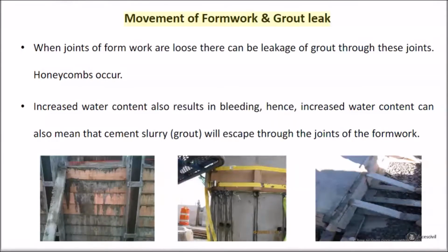Movement of formwork and grout leak. When joints of formwork are loose, there can be leakage of grout through these joints. Honeycombs occur. Increased water content also results in bleeding, hence, increased water content can also mean that cement slurry, grout, will escape through the joints of the formwork.